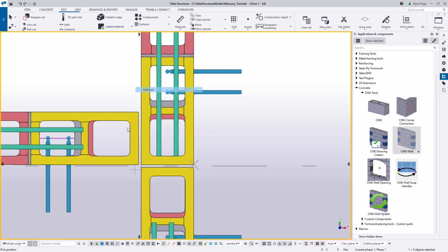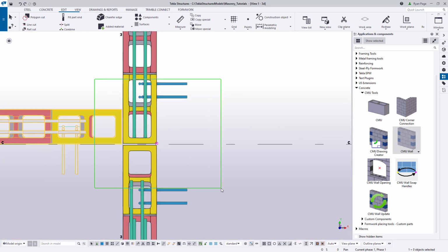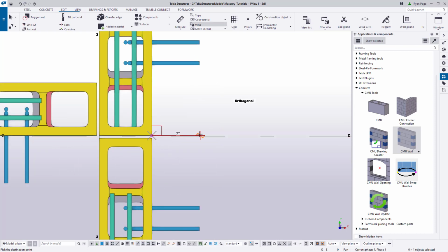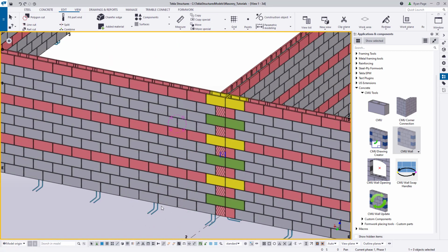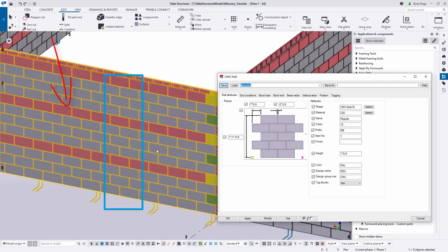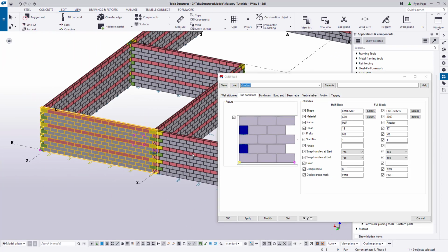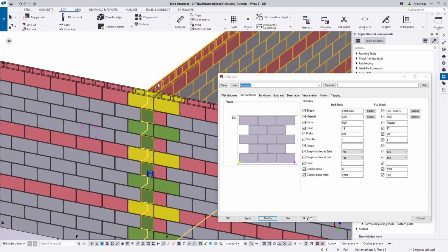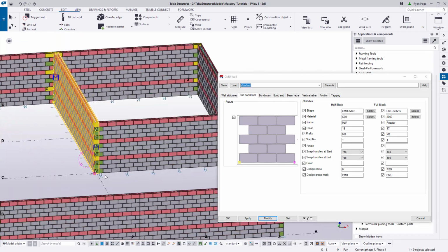For the segment we've just placed, let's ensure to select the wall and then select its endpoint. Right-click and use the Move command to nudge that out about 6 or 7 inches so that we get the extension of the half blocks into the wall. Let's go ahead and move back to the walls on E line and let's adjust our end conditions and remove those half blocks from the start point. And it looks like our courses line up with the perpendicular wall, so let's move down to the intersection of grid line 2 and grid line C.